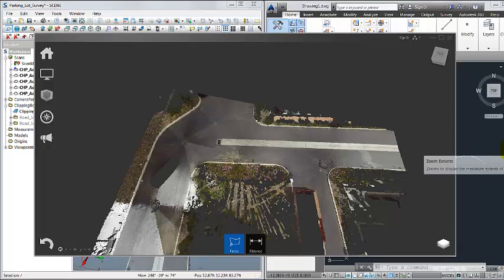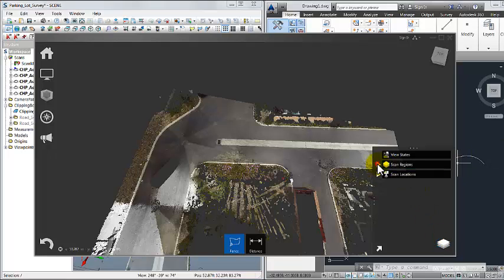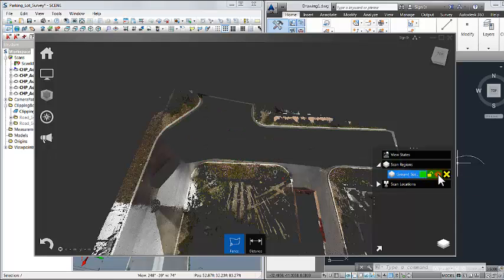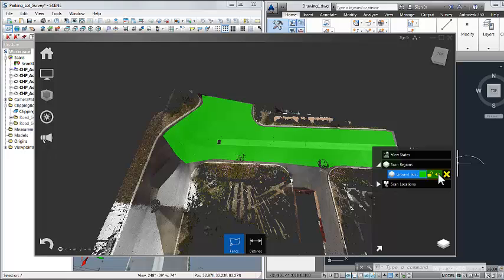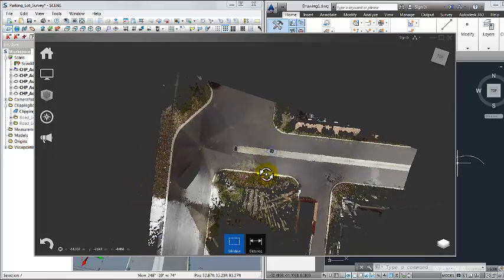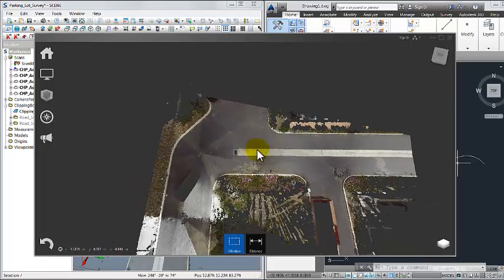And then go ahead and in recap, I've already got the region that I have selected as a ground surface. So I can go ahead and, I believe, hide everything else. So I turn that layer off. See if we can create a selection from that. Or even better, let's just create another sort of quick selection along the road here, create a surface from that.